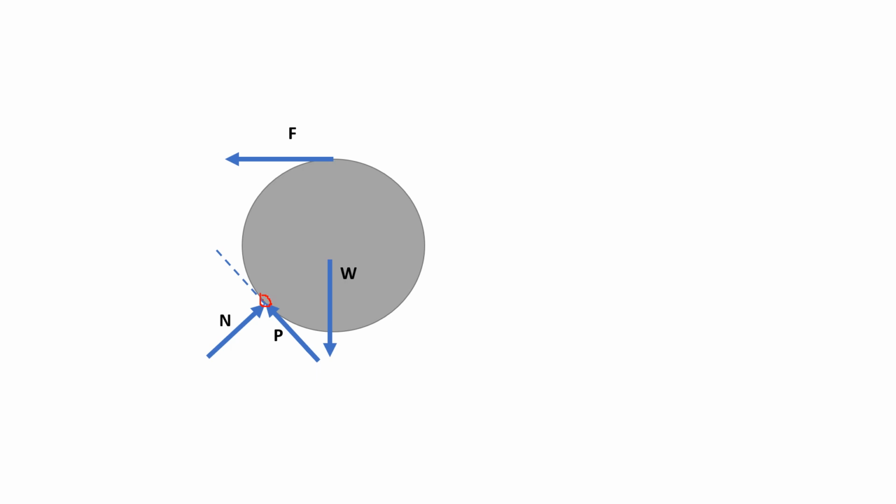Now, supposedly in the figure, we saw that the disk should be in contact with the ground here at this point. However, since the target of the force F is to lift the disk off the ground, once the disk is lifted off the ground, there's no more contact with the ground at this point. So we will not place any force at that point.